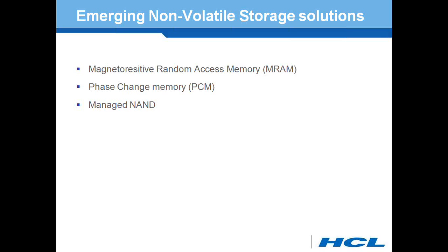The final one is managed NAND. Managed NAND is nothing but a raw NAND along with a hardware controller, which performs all the flash management features like error correction algorithm, wear leveling, and bad block management. It supports all popular interfaces like eMMC, SD, and other protocols. And these are the emerging non-volatile solutions upcoming in the market.